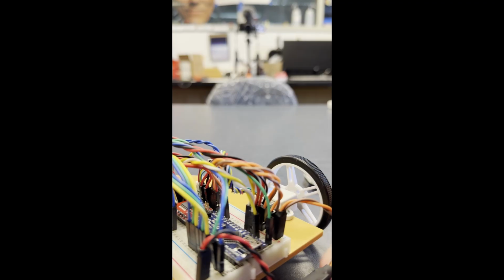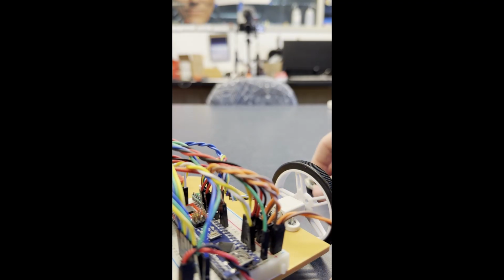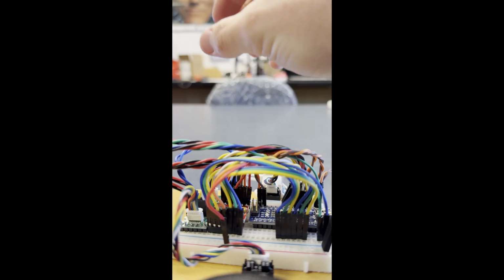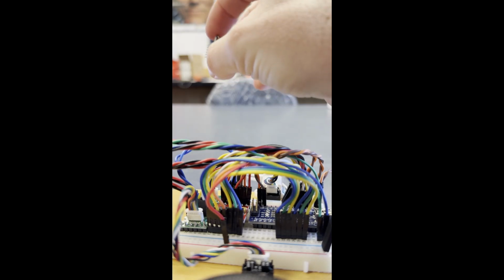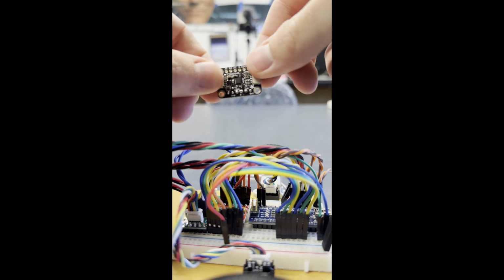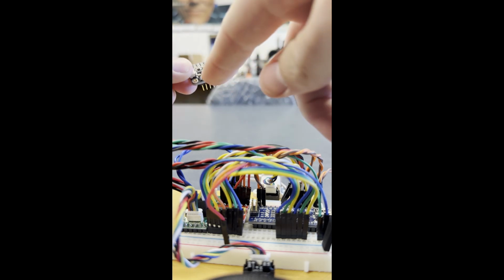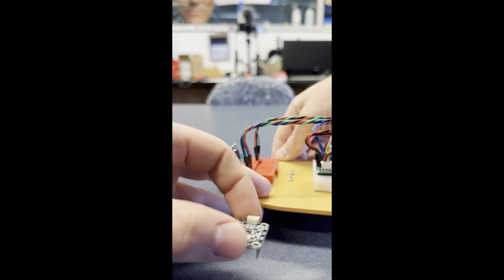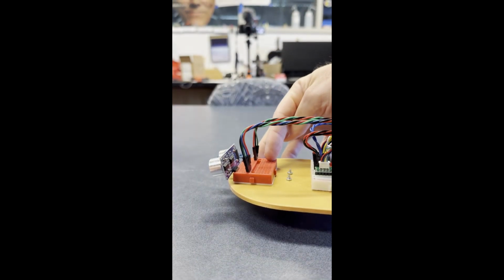All right, now I'm going to grab my rover. I'm going to take my IMU, and we're going to look at the mini breadboard, make sure we get things plugged in where they're supposed to be. So what we want is these pins we just soldered, the side with the SCL and SDA pins. We're going to make sure that they are on this side of this big old gap in the mini breadboard.